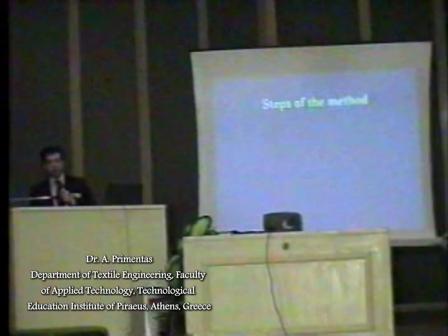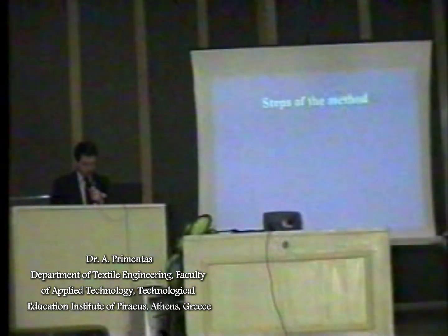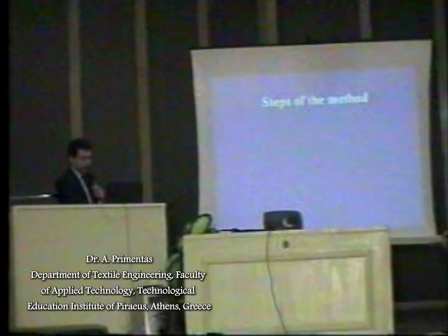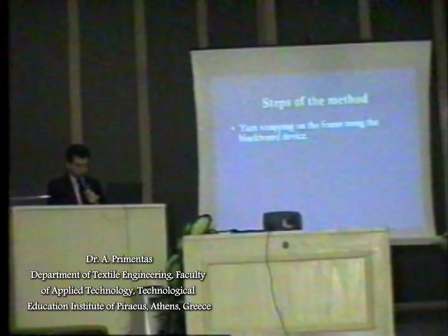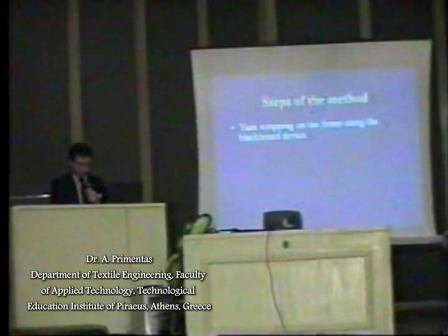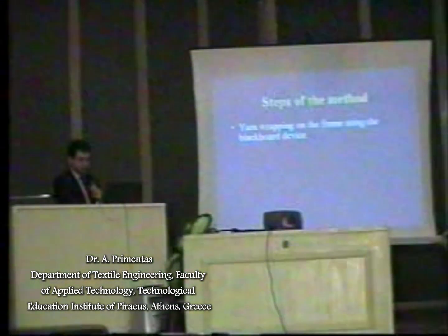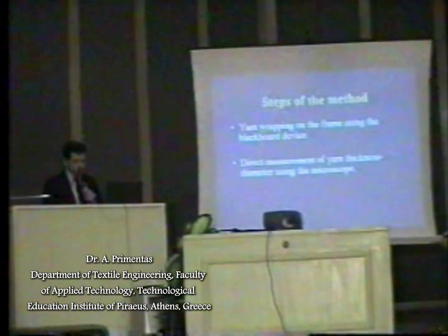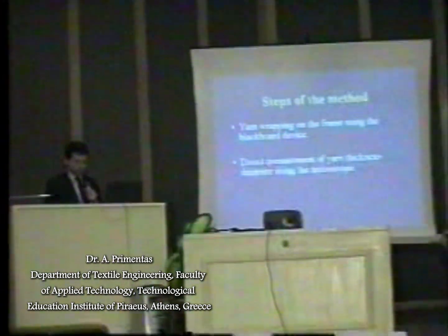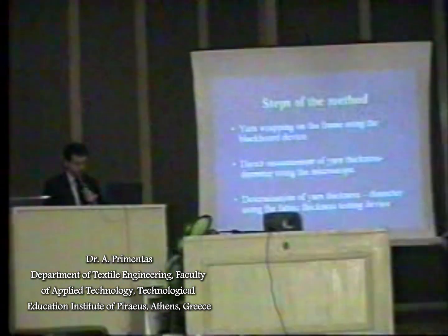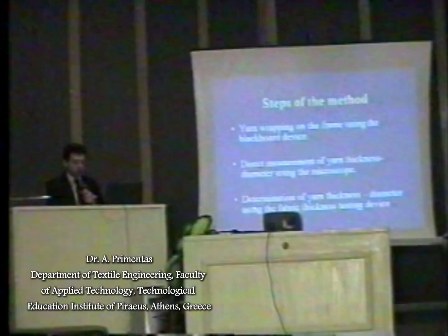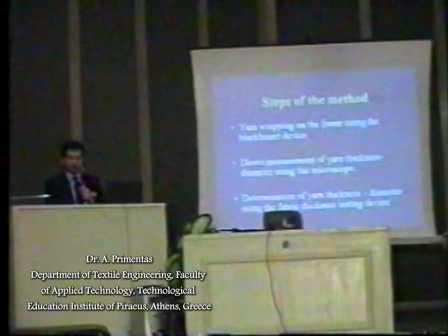And then here is the method. First of all, we have wrapping of the yarn on the frame using the blackboard device. Then, direct determination of yarn thickness / diameter using the microscope. And finally, determination of yarn thickness / diameter using the fabric thickness testing device.